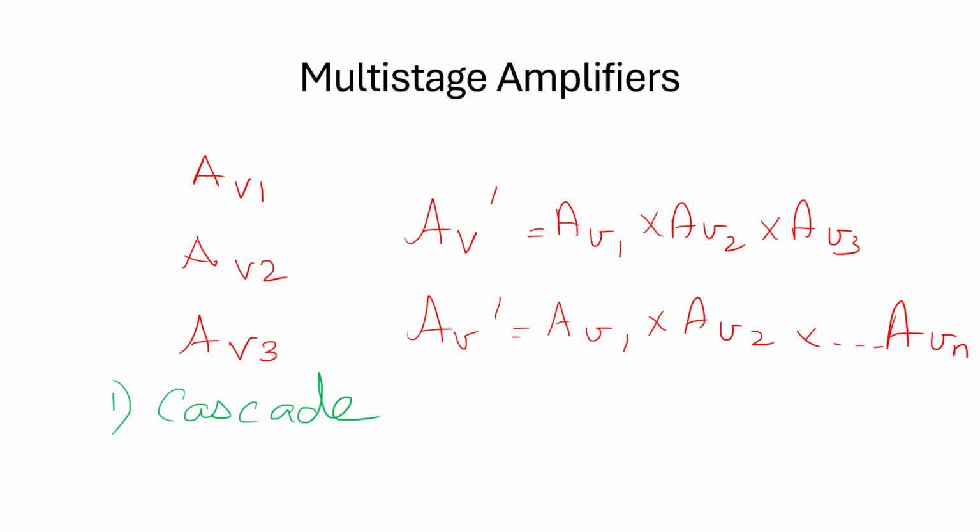In this kind of amplifier, the amplifier stages are typically connected in a horizontal chain, that is from left to right. The overall gain of the cascade amplifier is the product of the gains of each individual amplifier. So the connection can increase the amplifier's voltage gain, but also decrease the bandwidth. That is, the gain may increase, but at times the bandwidth may reduce. This is about cascade amplifier.